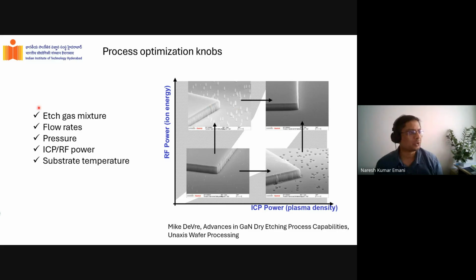This also goes back to redeposition, which somebody mentioned. If you have etching, you're also going to damage the mask. Sometimes mask can get sputtered. I think by now you must have been introduced to the word sputtering, wherein your ions can come and damage the mask, and some of it can fall here, and then it can act as a micro mask.